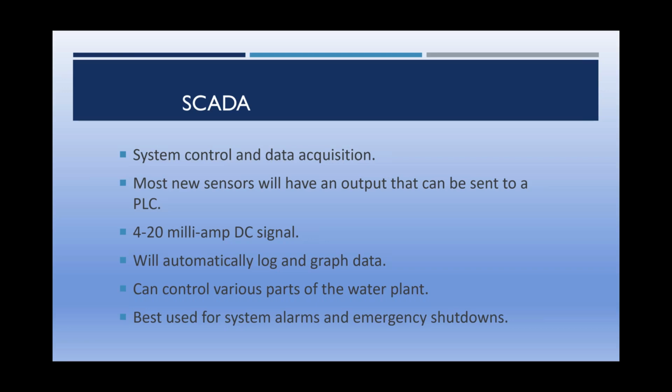But the system was 10 years old, and we could not get another screen that would fit the system. So the operator is trying now to run the system when he cannot look at any of these outputs manually. The flow meter did not have an output he could look at like we saw with those other, particularly the brass ones. The pressure sensor had no output other than going to the computer. The pump hours, again, just went to the computer. He couldn't directly read it off the panel. So he was trying to operate this plant completely blind.